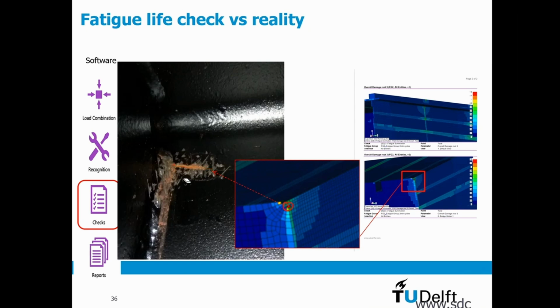This is the effect of a rat hole, and the advantage of a rat hole is, of course, you do not have welds in different directions joining at the same point, but the location of the end of the rat hole is important.